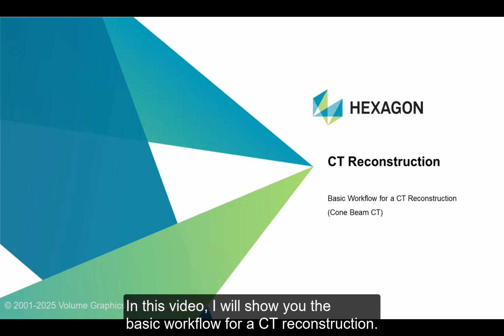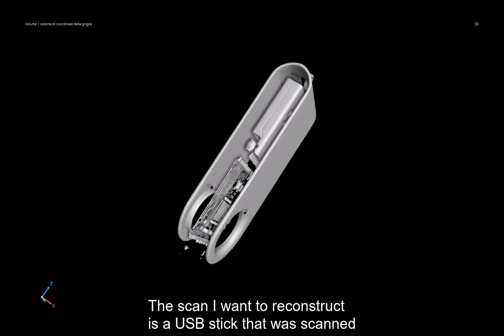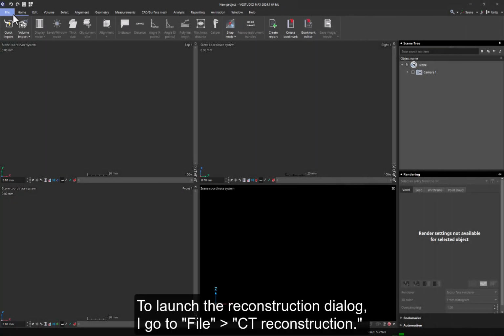In this video, I will show you the basic workflow for a CT reconstruction. The scan I want to reconstruct is a USB stick that was scanned in a cone beam scanner setup. First, I will open VGSTUDIO MAX. To launch the reconstruction dialog, I go to File, CT Reconstruction.